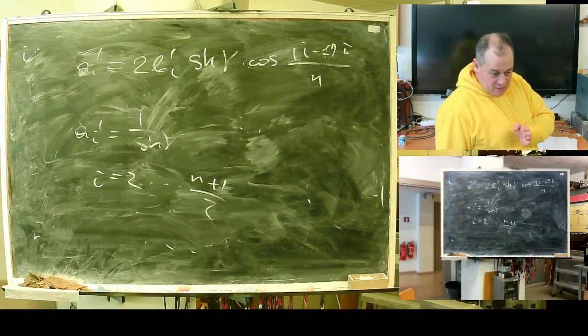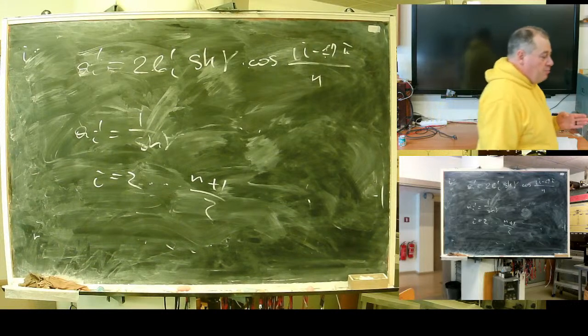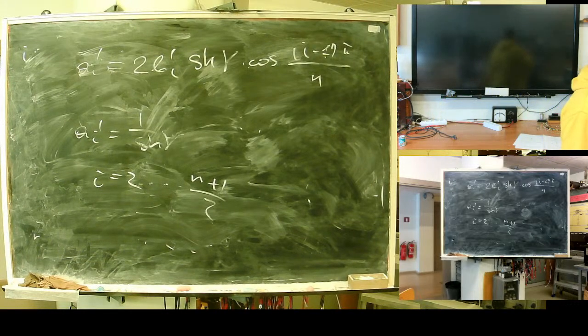Cheap, or some kind of special processor in the digital part, means we cannot afford high sampling rate. Low sampling rate means the Nyquist frequency is closer to our working area.